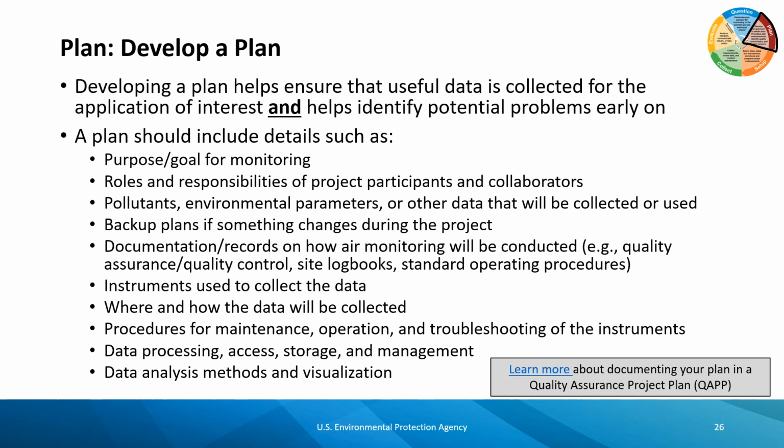5, documentation or records on how air monitoring will be conducted, such as standard operating procedures for operating the equipment, quality assurance and quality control procedures, site logbooks for field observations, etc. 6, details about what instruments will be used to collect the data. 7, details about how the data will be collected and transmitted to a storage location. 8, procedures for maintenance, operation, and troubleshooting of the instruments. 9, details about where data will be stored, how it will be processed, who will have access, and how data will be accessed and managed.